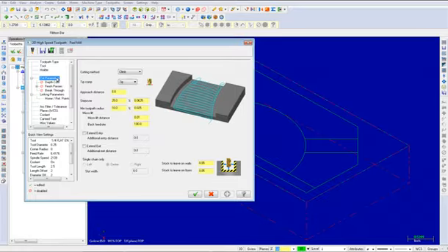Enter a min toolpath radius of 2.5%. Also, change the step over amount to 0.05 as shown. Next, enable the following options: Extend Entry and Extend Exit.